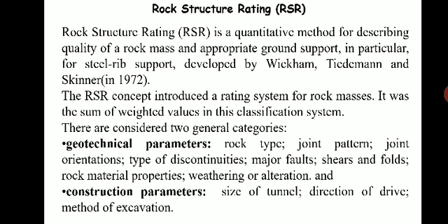Then next is the RSR, that is rock structure rating. So rock structure rating is again a quantitative method for describing the quality of rock mass and appropriate ground support, in particular for a steel rib support, which was developed by Wickham, Tedman and Skinner in 1972. So these people developed the concept of RSR, that is rock structure rating.